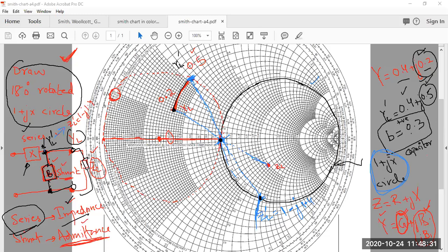But it's obvious that if I want to come to this point where I only have the resistive part, which is equal to 1, I have to cancel this part. Right now, I am at 1 minus j1.4, and I want to reach this point where I have only 1. So it means minus j1.4 has to be cancelled out.